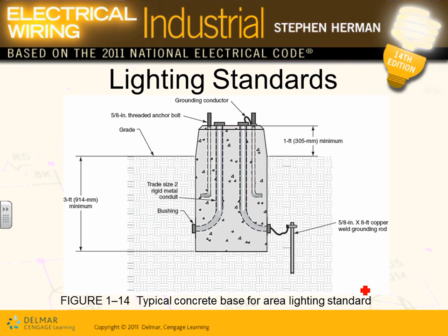You guys have used this one a lot with me. For lighting standards, since we're on the site, typically they have a standard like this where you can have your bolts. This is where your fixture is going to be sitting, on the pole; you bolt your pole here. Can you see how you have a grounding electrode conductor coming in here, tied to the bolt over here, and you bring your equipment grounding conductor.